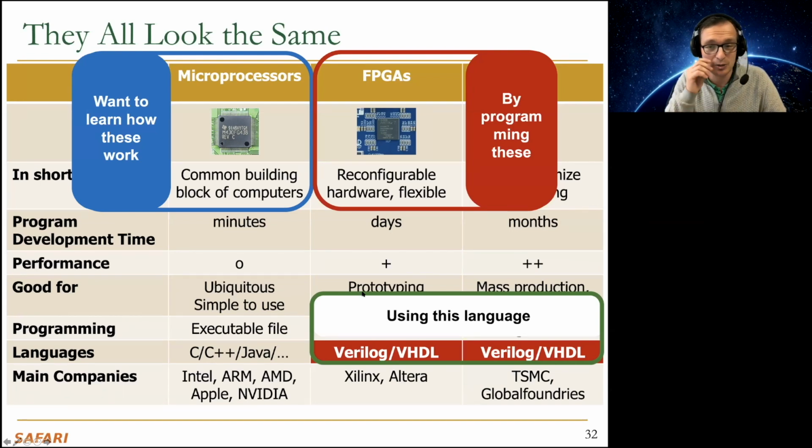There are efforts also to program FPGAs using high-level languages. In fact, that's the dream of many reconfigurable logic advocates. They want basically to take C, for example, or Java, or your favorite high-level language, and generate a bit stream of hardware, the connections to configure, by compiling C directly into that bit stream. It turns out that's not an easy task. It's doable, but efficiency is very low in terms of the created FPGAs because you're not using a language that's designed to express the hardware in an efficient way. So people are working on it, basically. This is called high-level synthesis, for example, from high-level languages.